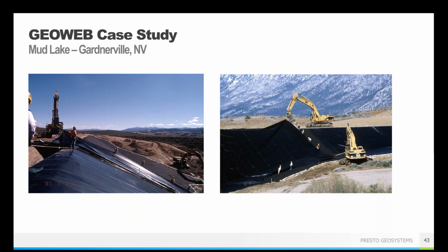In the left photo on the far left side, you can see the trench being dug there, and they terminated the geotextile geomembrane sandwich in that trench as well. So they were able to just sort of double up on that trench without having to dig two of them. So the geomembrane provides that nice impermeable waterproof barrier that's great for earthen structures. If you have one, totally good. We can work with it. If you don't have one, no big deal.